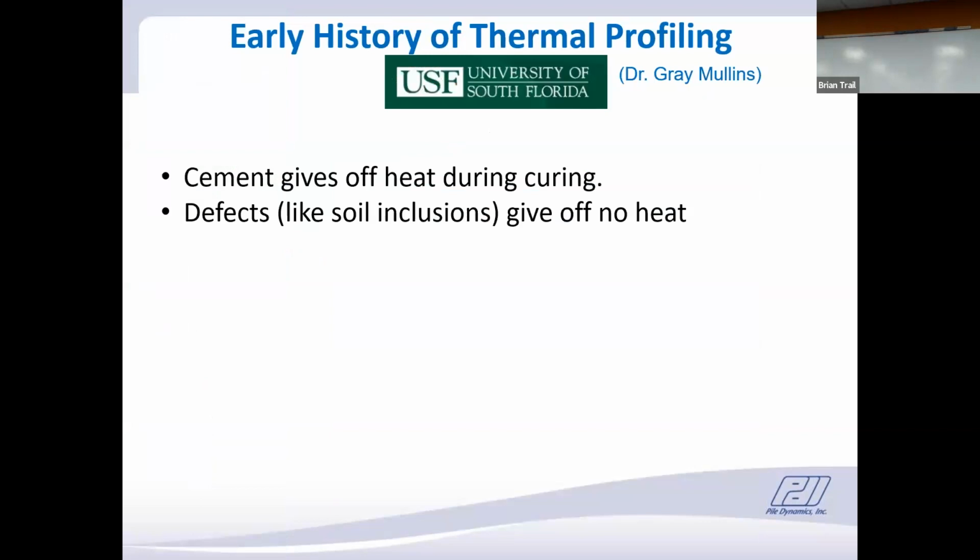So let's then turn to the new kid on the block, the thermal profiling. It was developed at the University of South Florida, which is in Tampa, by Dr. Gray Mullins. The concept is concrete, as we all are aware, gives off heat during the curing process. And if we have a defect like a soil inclusion, the soil inclusion isn't going to give off any heat. So we can tell if we have good quality concrete if we have high heat, and if we have a defect, it's not heating up. So that's the basic premise.